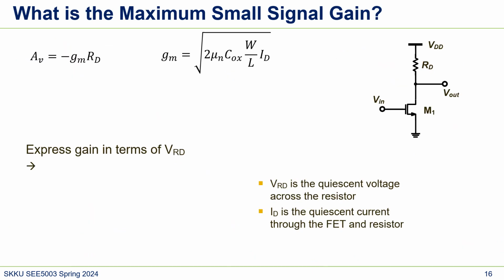We calculated the gain in the small signal model, and then we got this, right? What was the condition? Only when RO is a lot larger than RD. And then we can also represent the GM like this. You know how we can do that? So ID was 1 over 2 mu n COX W over L of VGS minus VTH squared, right? And then what was the GM?